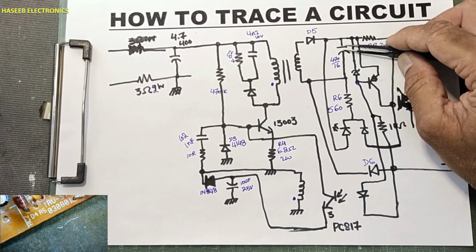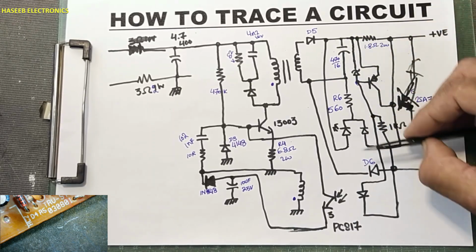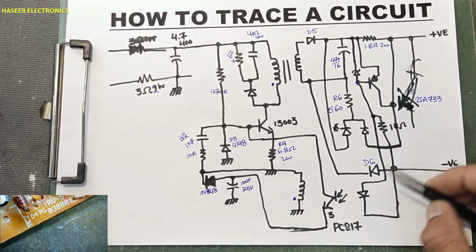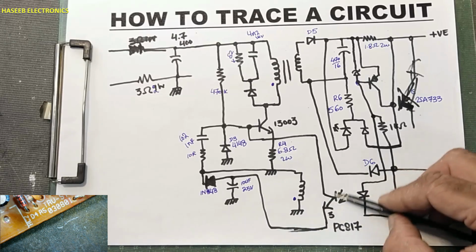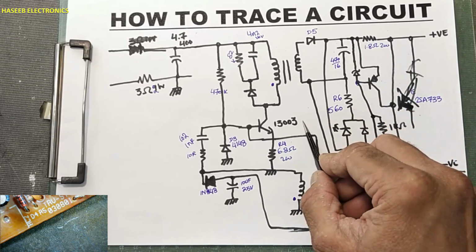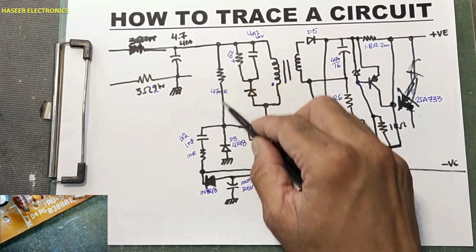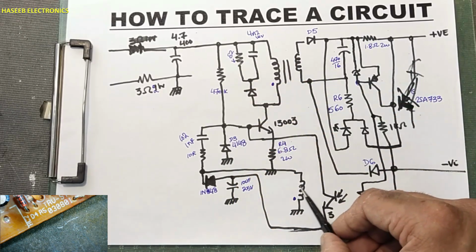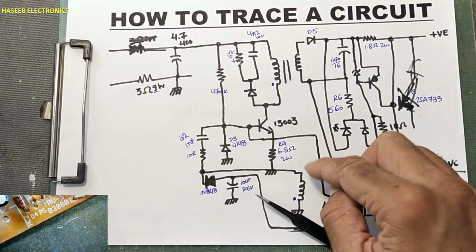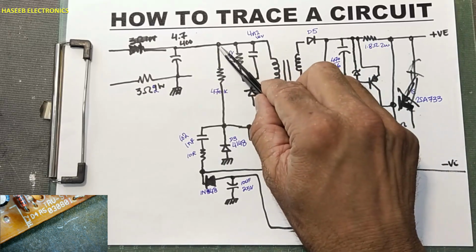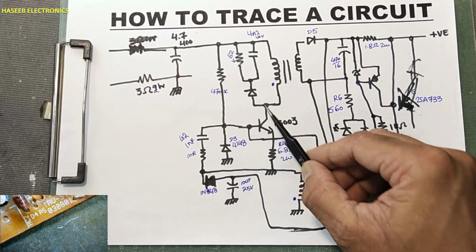At this time the voltage stored on this capacitor will run the load. As soon as the LED is released from conduction, because when voltage will drop, it will release this transistor. When it will turn off, at that time this line is now blocked. Again this end will start working. It will start to move into conduction, and it will assist to move into saturation, so that this transistor will start oscillation. First oscillation from this voltage, and then it will move to conduction.